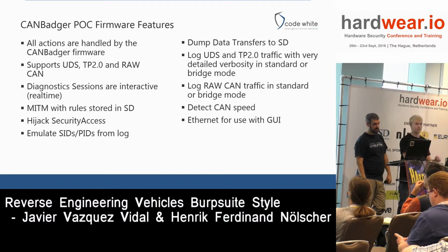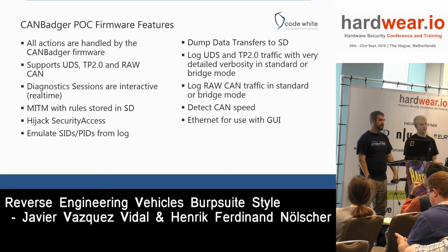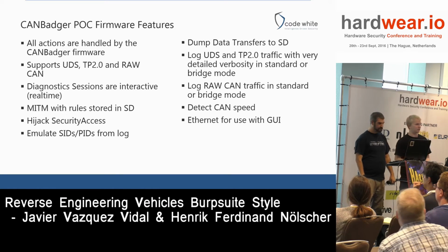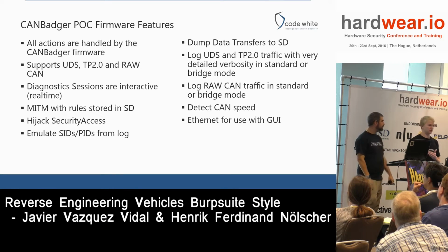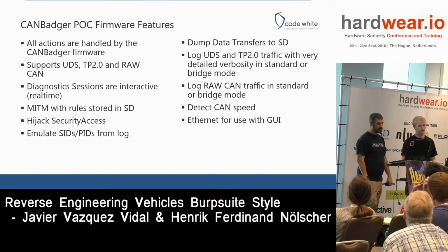It's a somewhat newish attack. It can emulate SIDs and PIDs from a log, so you can say, I will record me driving to the supermarket, and then you can replay this data. Well, actually not replay. For example, in the use case where you have a dongle that requests information from the car constantly, the emulator will wait for those requests and remember the point in time at which data was returned. We're going to get into more detail on that.